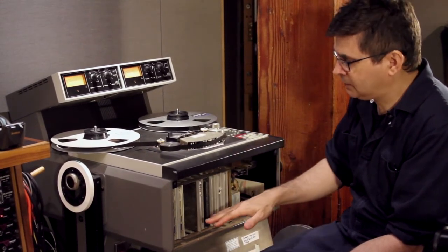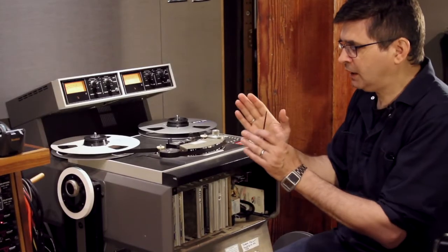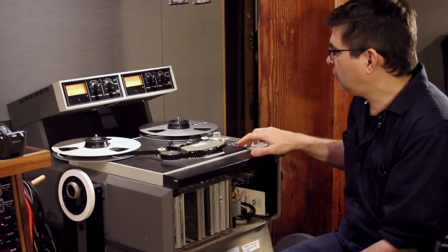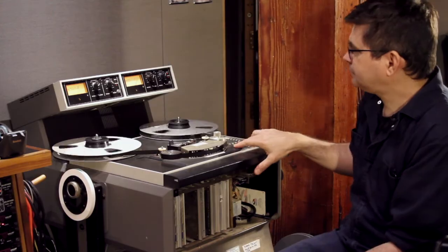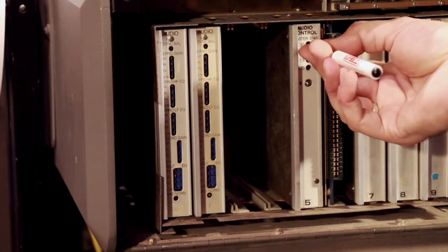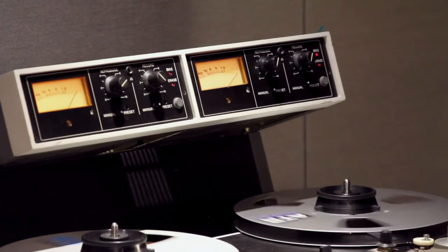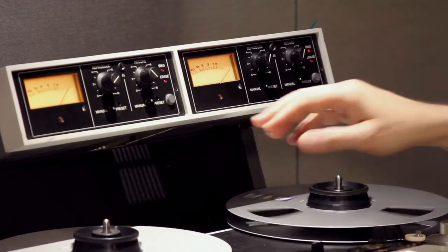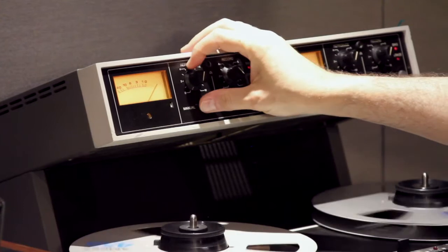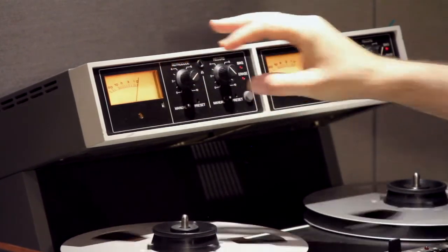The important thing is that all of these pots are being exercised over the life of the machine, and you don't end up with pots that are stagnant in one position and develop poor contact as a result. So I'm going to record the 20 kilohertz tone, and I'm going to adjust the master bias trim pot so that we get peak level. And the peak level here is quite high on the scale. So I'm going to adjust the output of the machine using the non-calibrated output so that the peak is resting at 0.